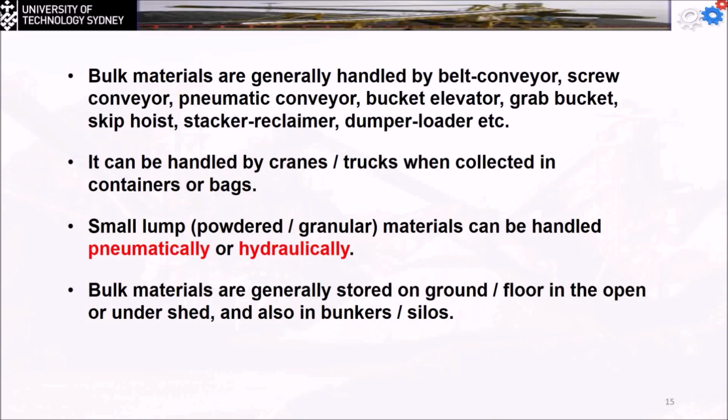Small lumps, like powder and granular materials, can be simply handled pneumatically or hydraulically. Pneumatically means we mix the material with air and send it through pipes, and then we can separate them later. Or we can mix the material with water, pump it to the other side, and separate them by a spinning process. Bulk materials are generally stored on the ground or floor, in the open or under a shed, or in bunkers and silos, depending on the material and how it can take the effects of the environment.